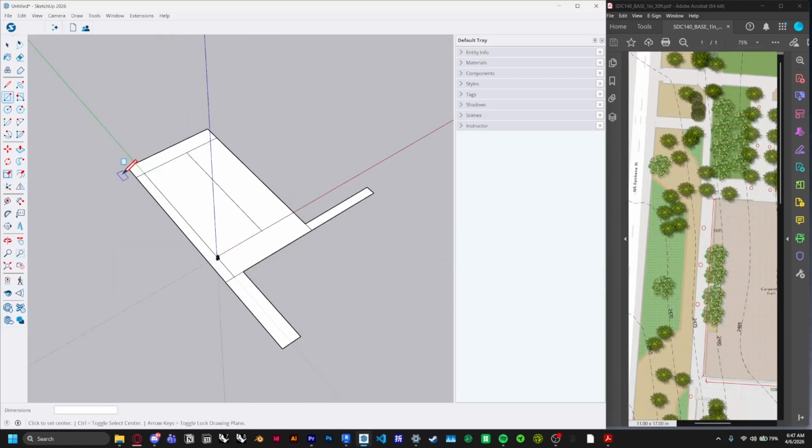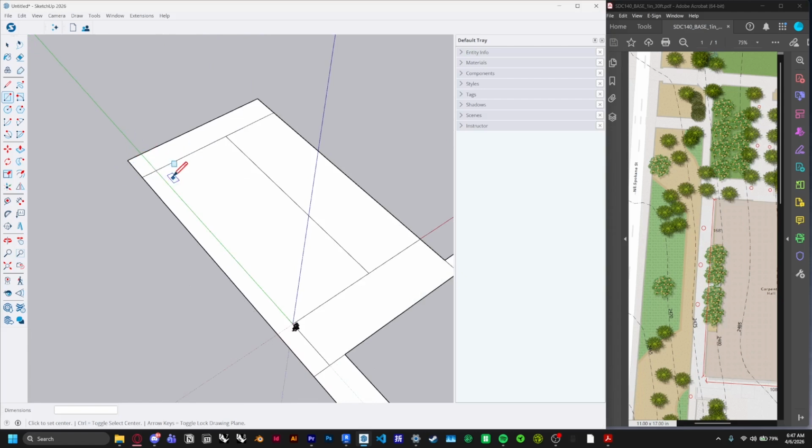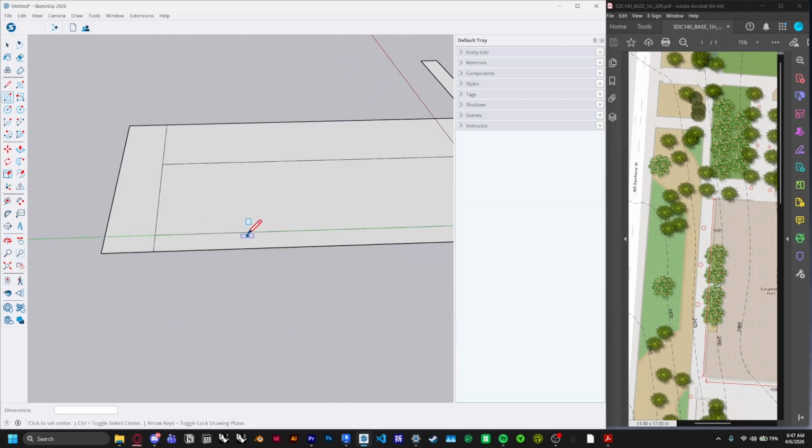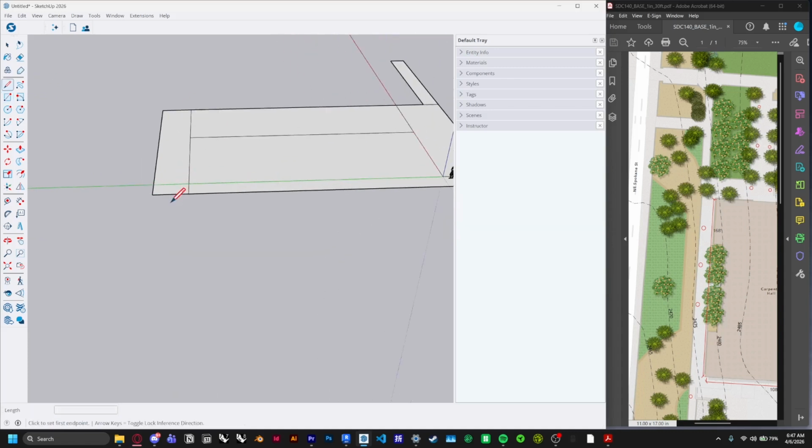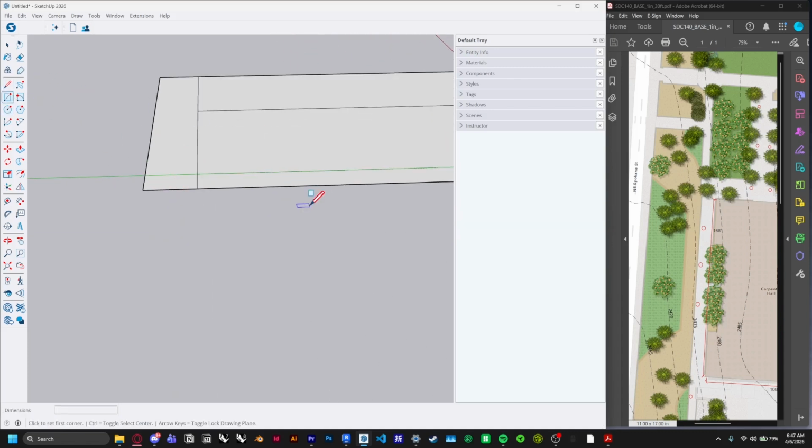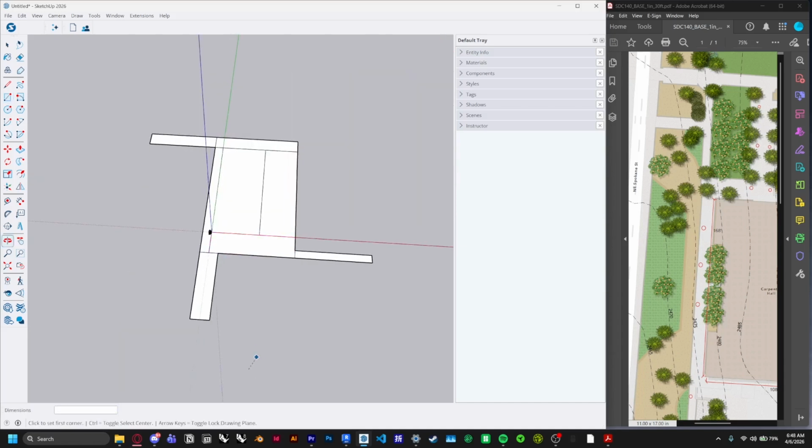Now for the bridge on this northwest corner, it's roughly 13 feet, but I'm going to go ahead and keep it 11 for now, and then because it's a bridge, we can expand it later if you want, but we'll keep it 11 for now. So go ahead and select the corner, and then once again, arbitrary 50-foot value, comma, by 11 feet. And there's also a pathway going north here, but I'm going to ignore that for now.